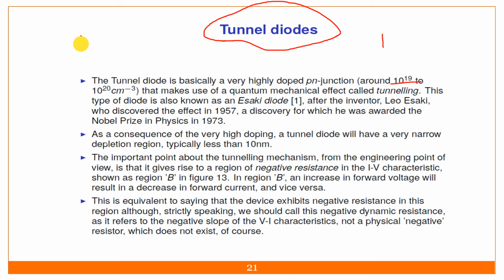What are we doing in this case? Suppose this is a 1 centimeter cube of silicon, but in microwave we normally use GaAs, GaP, or indium phosphide, like this. This cube is pure semiconductor material. Pure silicon or germanium is not practically used, since it is like an insulator at the intrinsic level.